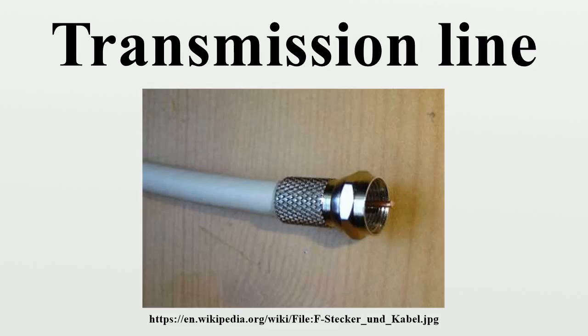Because the characteristic impedance of each transmission line segment Z0,i is often different from that of the input cable Z0, the impedance transformation circle is off-centered along the x-axis of the Smith chart, whose impedance representation is usually normalized against Z0. Practical types. Coaxial cable.